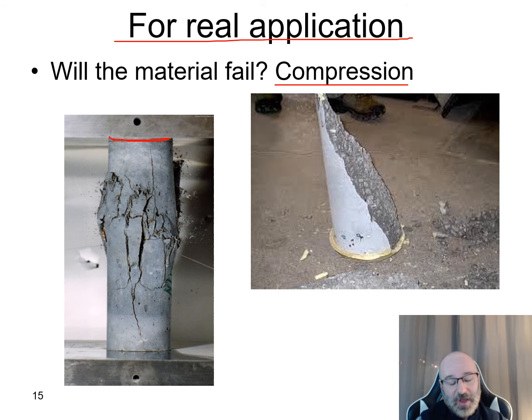And the issue is, especially up here in the Northeast where they may be using brine and salt, that could leak down through. The more porous the concrete mix, the more that can leak down, get to the rebar and cause corrosion. When the corrosion occurs, then all of a sudden there's a little bit of expansion, which causes a small micro crack around that in the concrete.